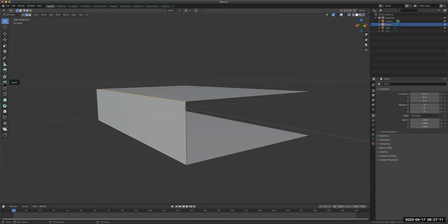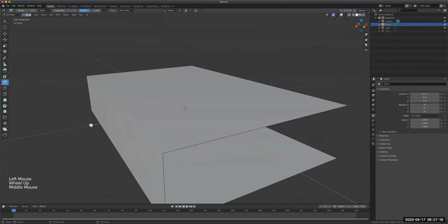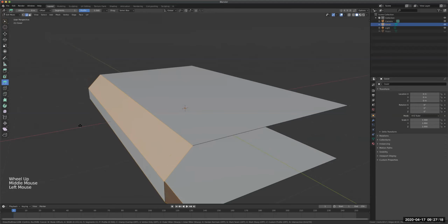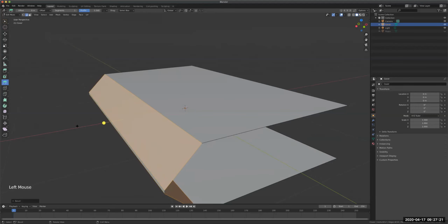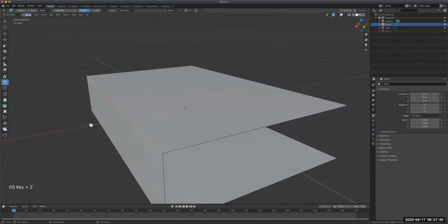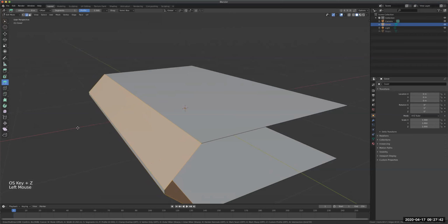The beauty of this tool, when you use it, you get this yellow little handle that you can pull, okay? If you're using right-click bevel, then you have to move the mouse. So it's a little bit more, in a way, interactive, but you don't get controls like this, okay? But if you press this again, that's a second bevel. So be careful with that, all right? It doesn't allow you to rest and stop and make changes, not unless you click bevel right here and then you access the control over here.